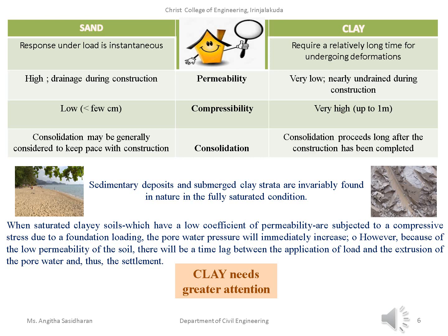Sand is more of a coarse grained type, and if it is clay, it will take a relatively long time to undergo deformation. And what about the permeability of sand and clay? Permeability will be high for sand. It will allow water to move through it, and even during the construction period, drainage will happen. That means the water can drain off from the soil during the construction.